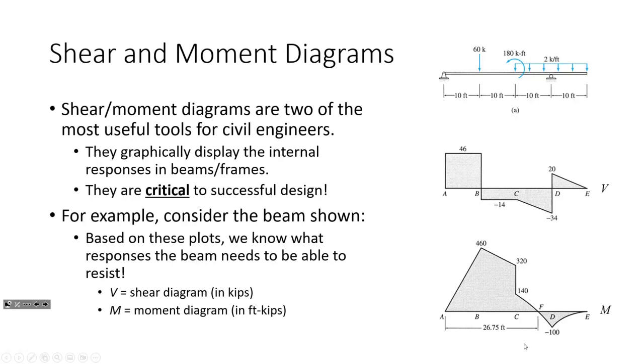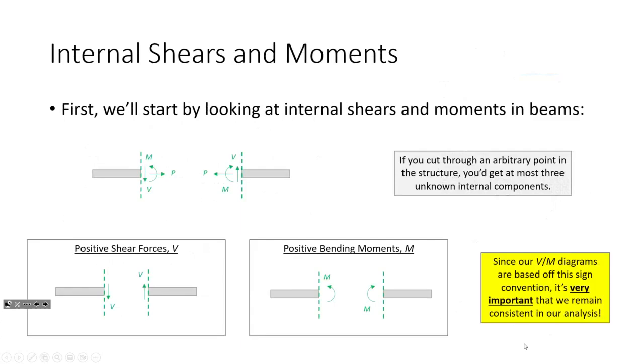These are, again, very seminal skills. And just about every single beam or flexural element that you design, you're either plotting a shear and moment diagram, or if it's a very simple case, you're using some plug and chug expressions to determine maximum shears and moments, but again, those are based on shear and moment diagrams. Now, again, a shear and moment diagram is a plot of the internal shears and moments. So the first thing I want to do is look at those internal shears and moments at particular points in the structure.